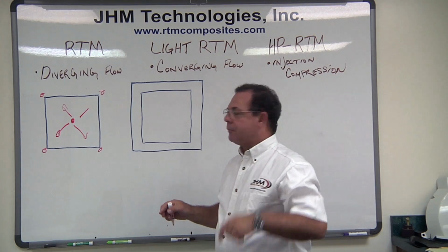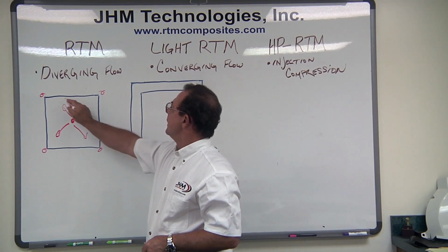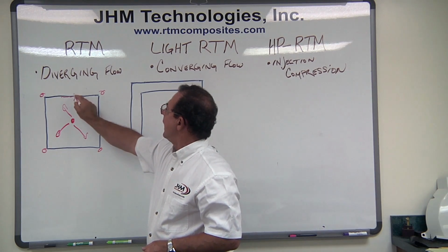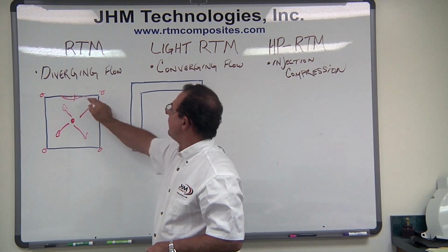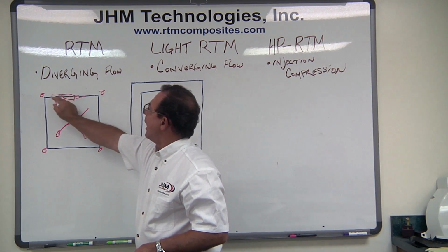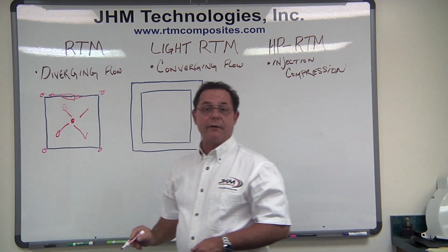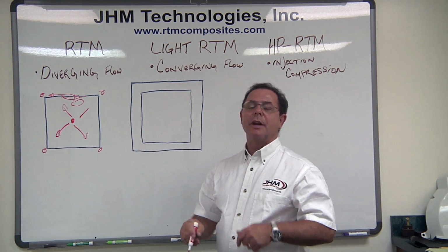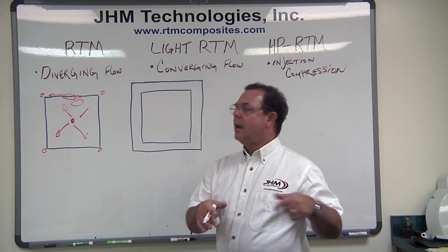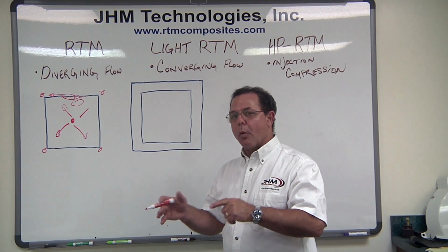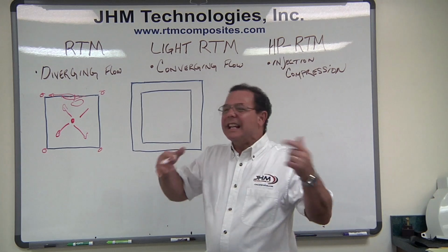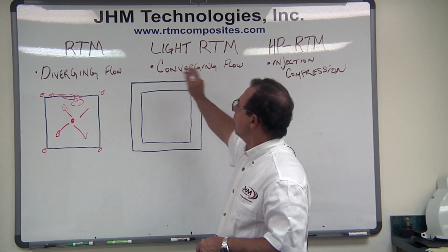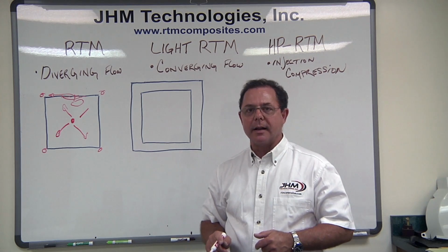In that element of design, our concern is the fiber on the edge. If the resin gets to an edge and there's void of fiber there, then the problem is the resin can racetrack to a vent and leave a dry spot. It was the historic problem. When I say was, it still is today. But what we have adopted today, more than anything in anything that's changed, to say that something has changed, is when we go to the light RTM design.